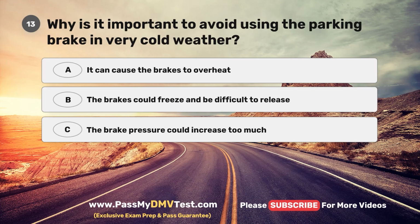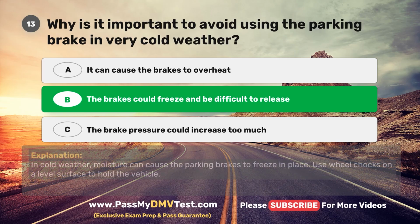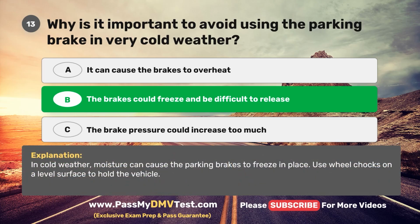Question 13. Why is it important to avoid using the parking brake in very cold weather? A. It can cause the brakes to overheat. B. The brakes could freeze and be difficult to release. C. The brake pressure could increase too much. The correct answer is B. The brakes could freeze and be difficult to release. In cold weather, moisture can cause the parking brakes to freeze in place. Use wheel chocks on a level surface to hold the vehicle.